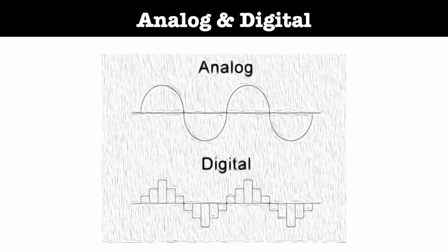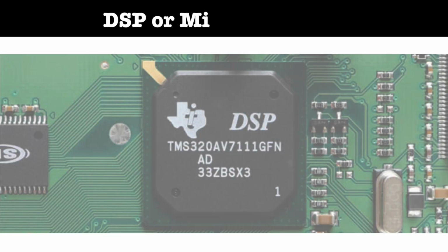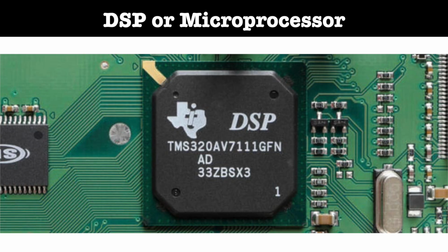Digital, which are immune to noise and configurable. The bandwidth is obviously smaller than the analog controller and it depends on the sampling frequency. Then we have DSP or microprocessor controllers having flexible lower bandwidth compared to above. DSPs perform faster operation than microprocessors. With DSP or microprocessor, complex estimations and observers can be easily implemented. So, this is the advantage of DSP over both analog and digital.